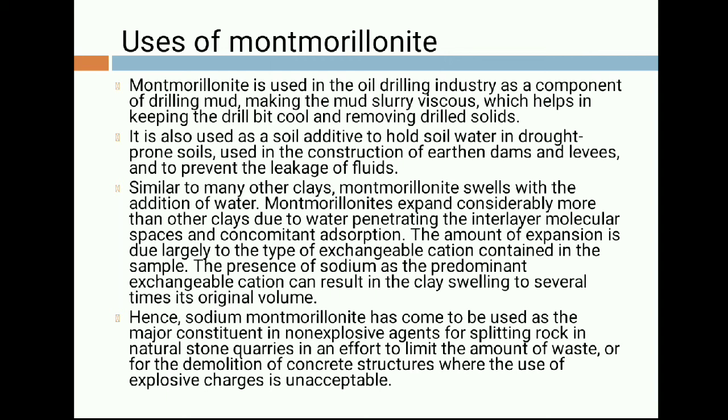Because of its more expanding and swelling property, it is not possible to use Montmorillonite in case of any structures, but based on this kind of property, it can be used in other kinds of applications. It is also used as a soil additive to hold soil water in drought prone soil, used in the construction of earthen dams and levees, and to prevent the leakage of fluids.